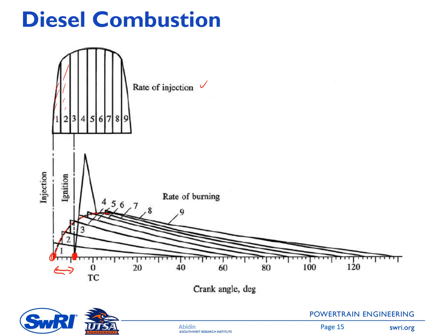The mixture that is injected and ready to be burned between period A and period B will control the spike of the heat release rate. You can see also the burning timing for other segments, for example segment number 9. This is showing the burning of segment number 9 there.